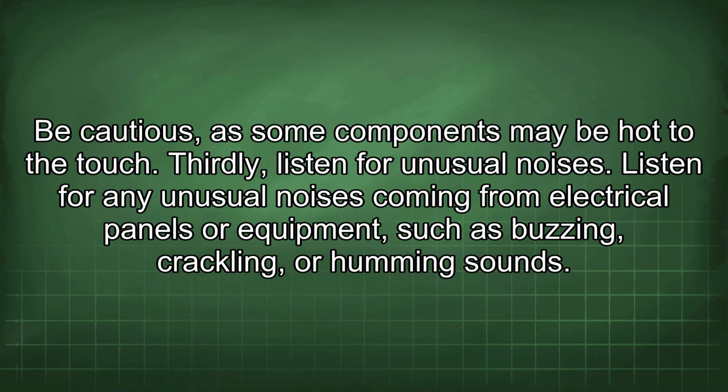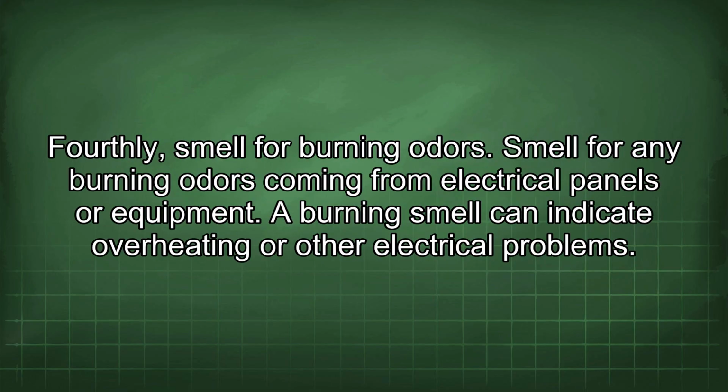Thirdly, listen for unusual noises. Listen for any unusual noises coming from electrical panels or equipment, such as buzzing, crackling, or humming sounds. Fourthly, smell for burning odors. Smell for any burning odors coming from electrical panels or equipment. A burning smell can indicate overheating or other electrical problems.